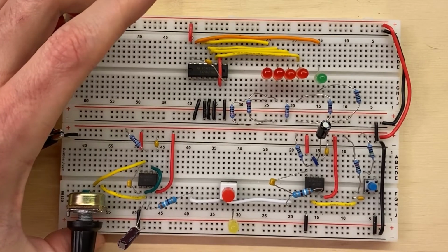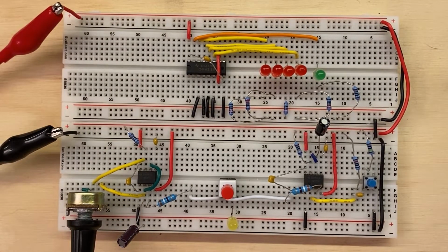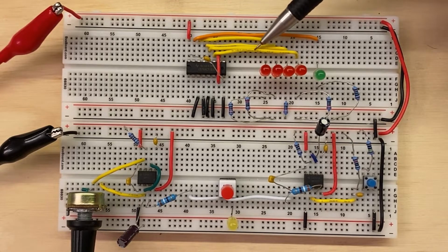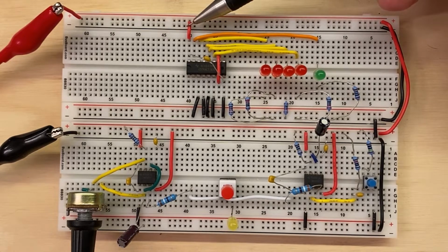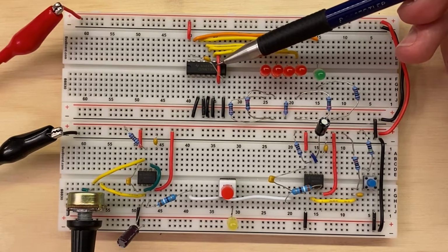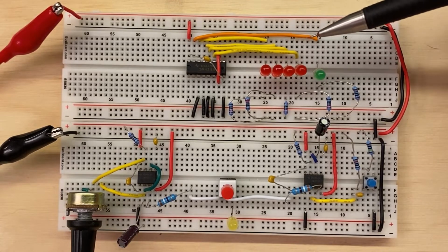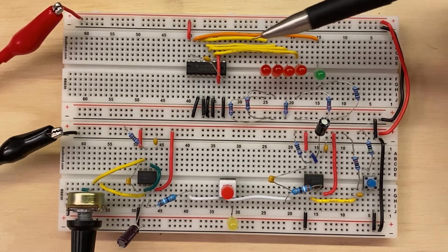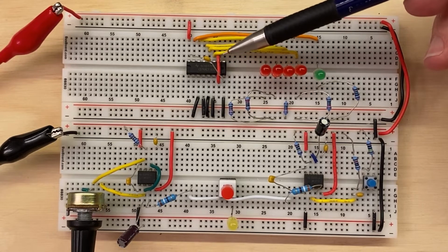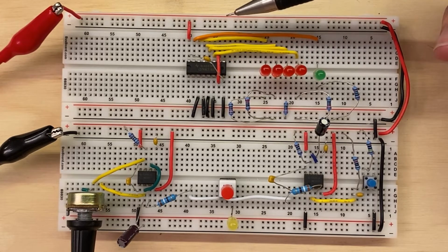So let's check it out on the breadboard, which I've got set up right here. Okay, so these 4 LEDs represent the output. So we have Q0, 1, 2, and 3, and they follow these yellow wires to the pins over there. Of course, we have our power pins right here on either side, and this red wire connects the 2 enable pins, the T and PE pins. And so for our chip to work, we're going to have to set both of these pins high. I've just connected them together, so we only need to use one jumper to set it high or low.